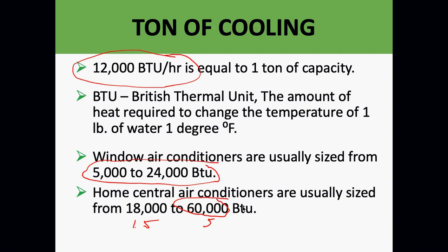So most commercial units, okay, and I'm not going to say all, because again, there's exceptions to every rule. Most truly commercial pieces of equipment have a 3-phase compressor. Okay, and again, they also do have units in commercial buildings that are only single phase, but most of the heavier, over 5-ton units are going to start having 3-phase. So you got to be careful about that.